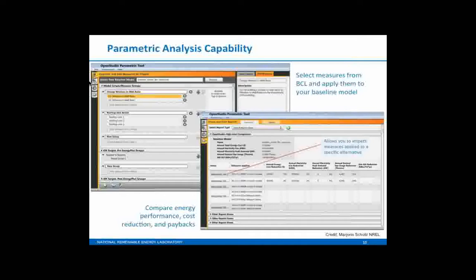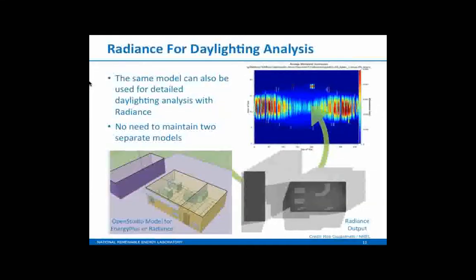Another thing that we've been working on over the last couple of years is Radiance integration into OpenStudio. So most of you are probably aware of the simulation capabilities that are intrinsic to EnergyPlus. They're not very good. They're somewhat crude, and there's all kinds of limitations on the daylight simulation capability in EnergyPlus. Whereas Radiance is almost unlimited in terms of complexity of form and materials and types of analyses that you would want to do in terms of the daylighting and electric lighting analysis.